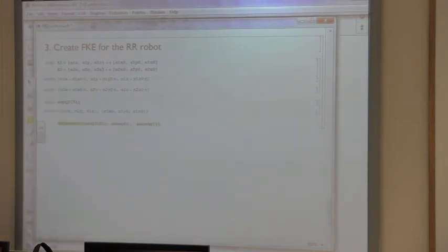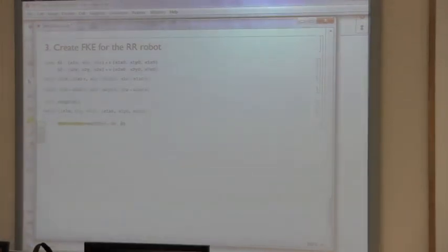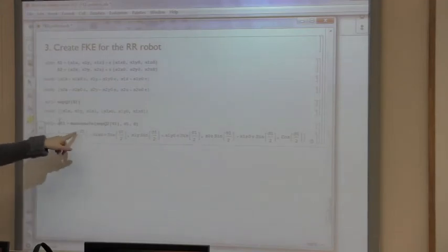So it's the dual vector, and the angle will be just unknown also, so we are going to call it theta 1 for the first axis, and then the slide along the joint is 0 because it's a revolute joint. Okay, so this creates our first quaternion, and let's call it, this is the rotation about axis 1, QS1. Okay, and everything is unknown because we need to find those.